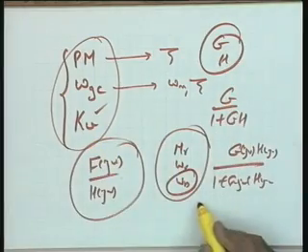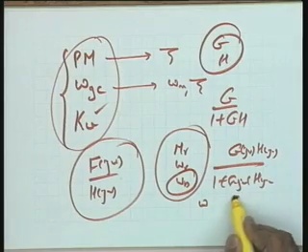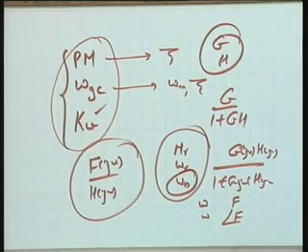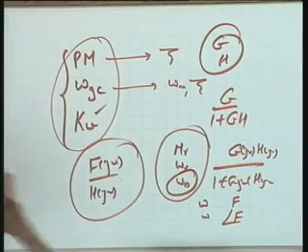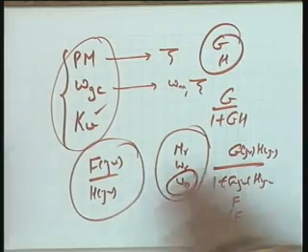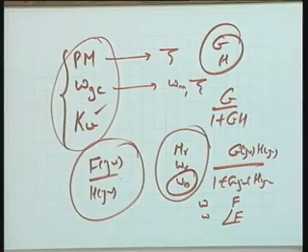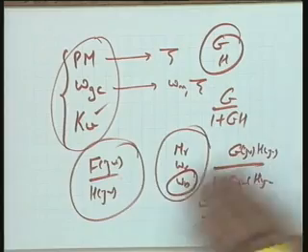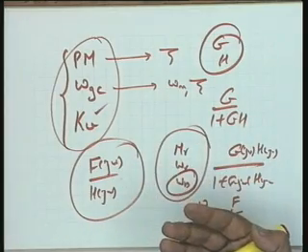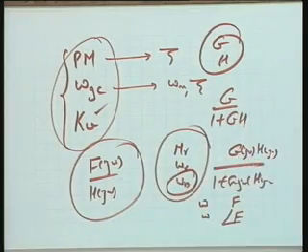So if you have omega versus F, omega versus phase angle, and H(jω) is already known to you, omega versus H, omega versus phase angle of H, then it is simply an algebraic manipulation, F by H. The magnitudes will get divided, the phase angles will be algebraically added. Yes, please. But it is an exercise which normally is not easy to do, and therefore it will be better to write software immediately so that it is usable for calculating this. This is the comment I am making.